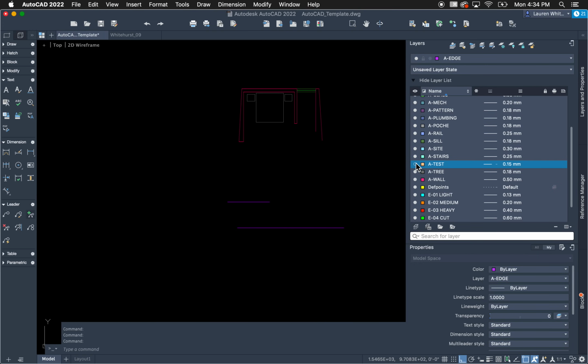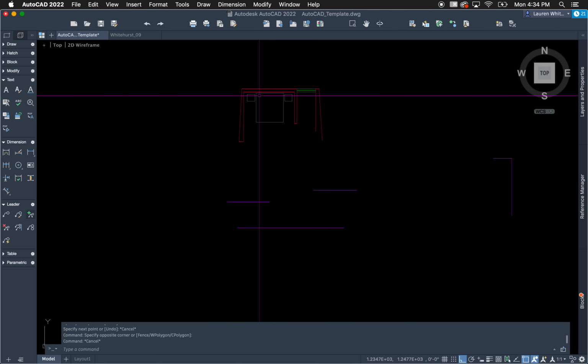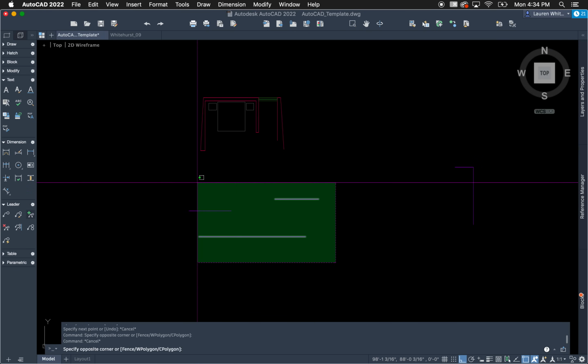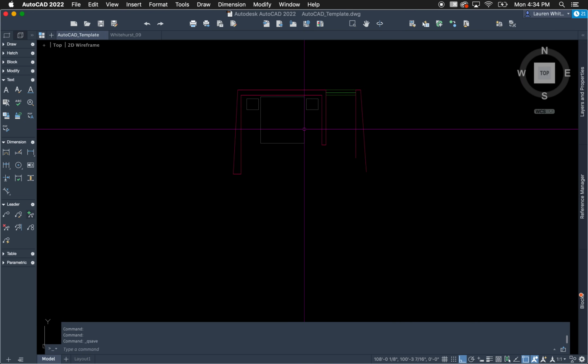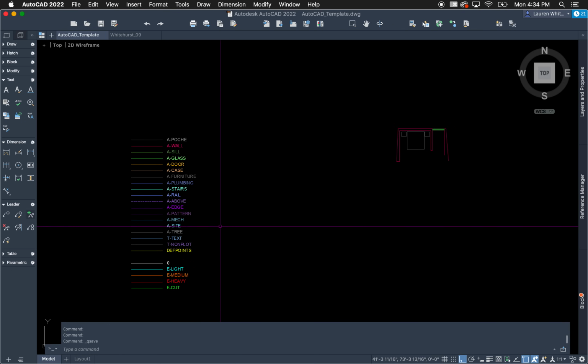And what's nice about that is when you go to print, everything on that layer itself will have those properties. So it's a nice tool to globally control things. Sometimes when you're printing, you might decide, oh, actually, it's not showing as thick, and you can change that globally. A lot of offices will have standards set up so that you're not having to define that every time. It's a known thing, and you just use the correct layers as you're drawing.